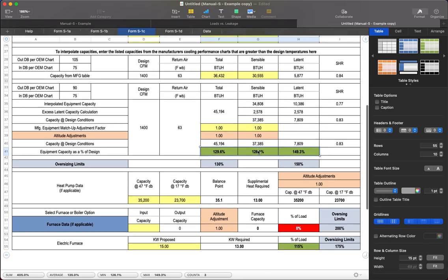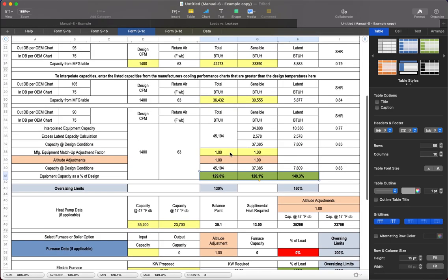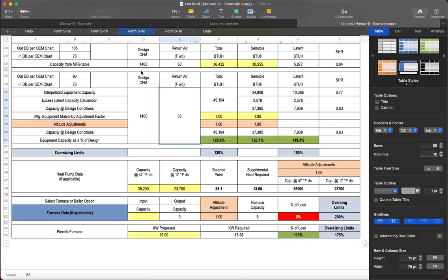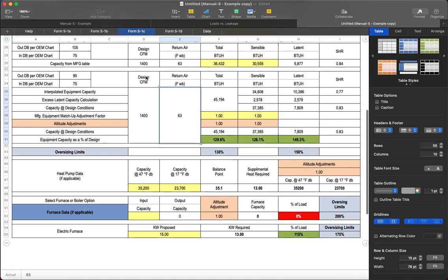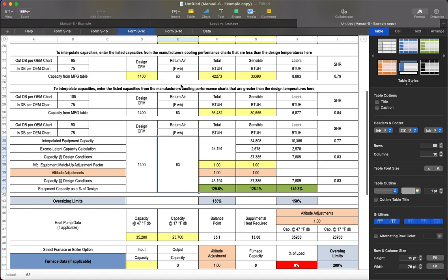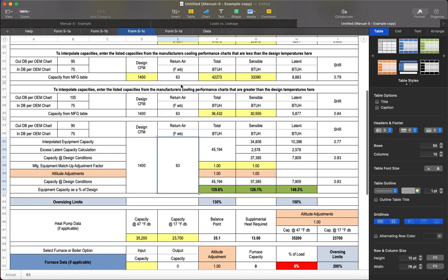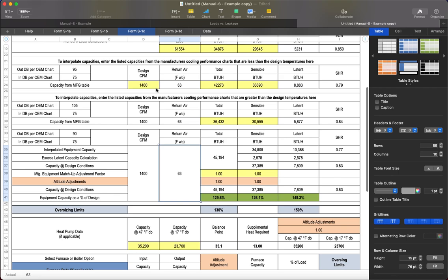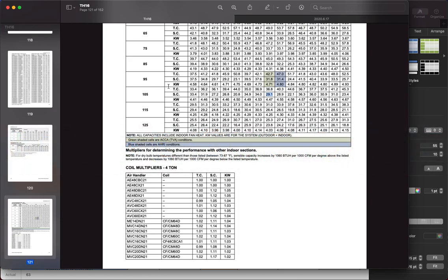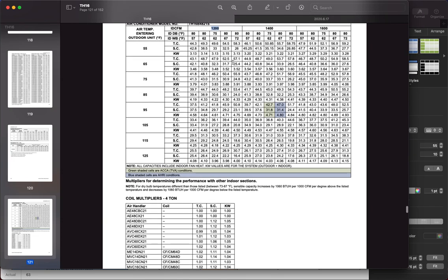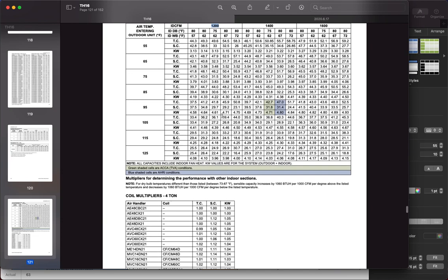The thing I don't like about this is, because for this project, which are details that you don't quite know, it's primarily an existing system. We are adding a little bit of ductwork, but I'm not trying to reinvent the wheel. So since my manufacturer also provides data at 1200 CFM for this, I want to see what that looks like.